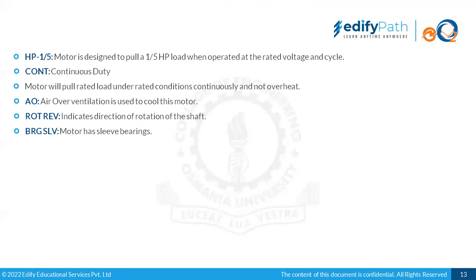The motor will pull rated load under rated condition and not overheat. So if continuous is mentioned and the loading is as per the mentioned conditions, then it would be continuously running and will not overheat. But from time to time, we have to take it for overhauling to check the bearing condition and to grease it properly, so that reliability is higher in the long run.